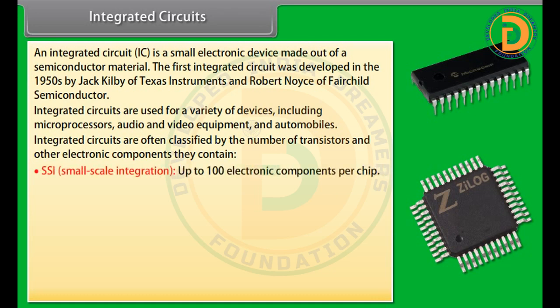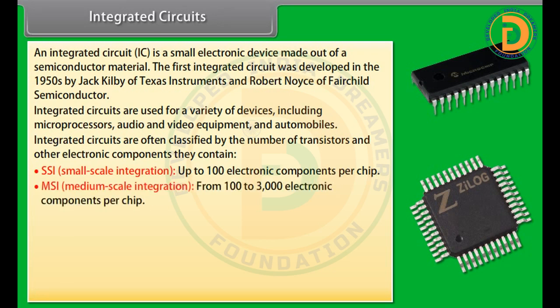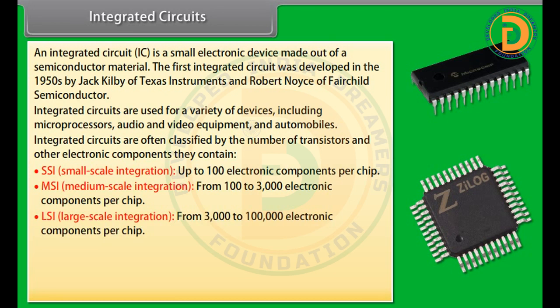SSI. Small scale integration. Up to 100 electronic components per chip. MSI. Medium scale integration. From 100 to 3000 electronic components per chip. LSI. Large scale integration.